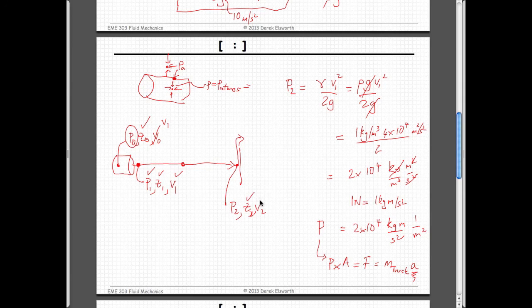If you know the elevation and you know that you've killed all the momentum of this stream, just like this ball hitting the wall and the velocity going to 0 as it hits the wall, mass times velocity, you've killed the momentum. That's exactly what we're doing here: as the velocity goes to 0 at the stagnation point, we're left with only one unknown to determine. And that's really all we need to know about Bernoulli.